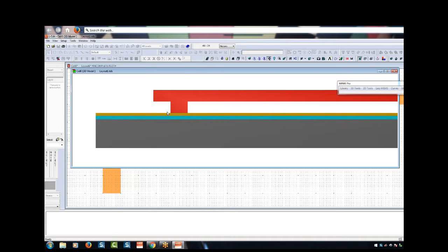Poly 0 is a little thinner than the Poly 1. And we made a hole with anchor in the sacrificial oxide, which used to be in between here. You don't see it anymore because it processed it away. And you can see that this hole was filled with the Poly 0 and you formed an anchor. So now this cantilever doesn't float away.